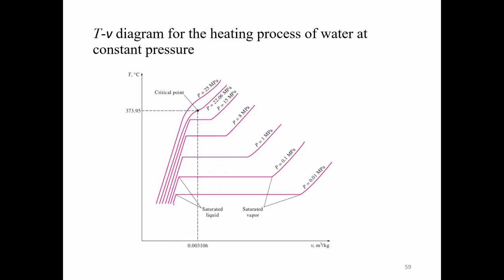Now if we continue that experiment with different temperatures and different pressures, we will get something like this, right? There's a point where this flat region, when we increase the pressure, reduces gradually. So there is a particular temperature, particular pressure and particular volume where this line becomes a point. That point we normally refer to as the critical point, right? Beyond that point you can't convert gas into liquid.